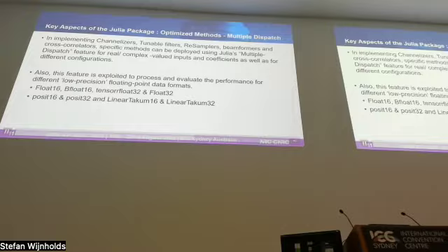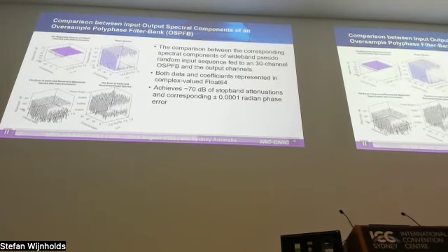Note that posit and linear takum are second-order floating point number formats, and their arithmetic operations are implemented through corresponding Julia wrappers. The oversampled polyphase filterbank function was verified through numerical simulations using test signals made of sinusoids with known magnitudes and phases and represented with Float64 format. The criterion is to compare the magnitude and phase of the input sinusoid at a specific frequency with that of the corresponding channel. Correcting for magnitude variations due to passband ripple was necessary before comparison of the magnitude.